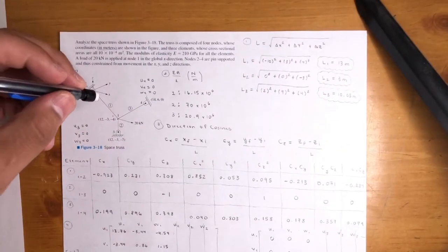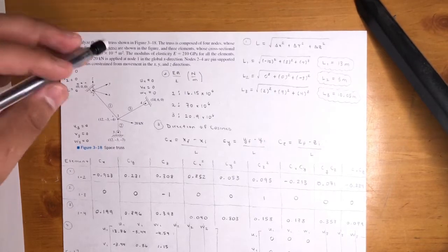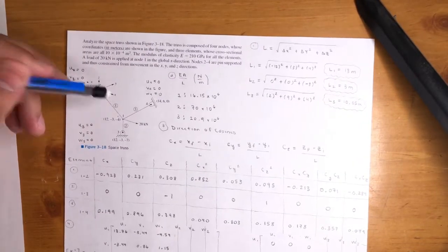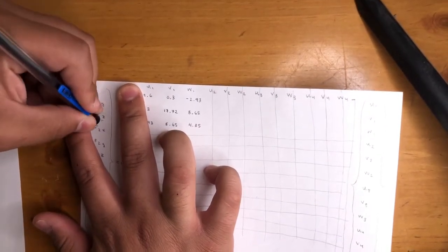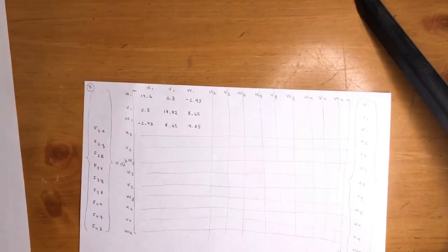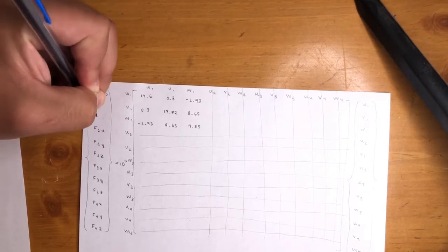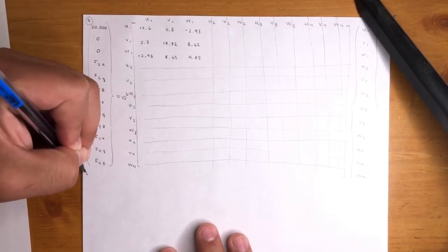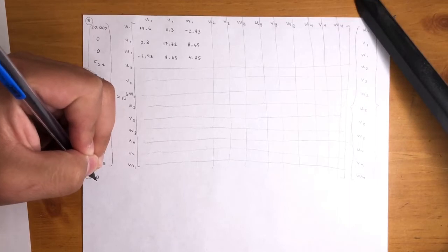So now we're gonna go ahead and apply the force boundary conditions. So right here, it says we have 20 kilonewtons, so 20,000, right? We care about newtons, is applied at node 1 in the global x direction. And that's it. There's nothing else in the y or z. So we're gonna have, check it out, a lot of erasing, but it's 20,000 positive, right? And then 0 and 0. So now we have 3 equations and 3 unknowns. So we could go ahead and start assembling those equations to find our u1, v1, and what do you call it?